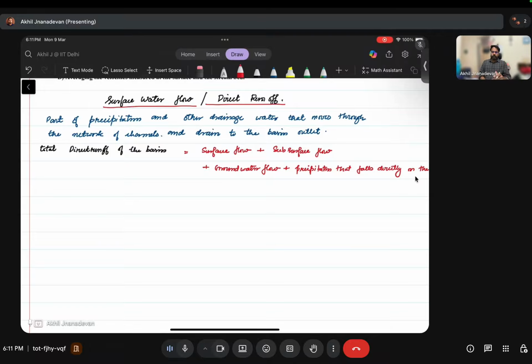Now we will be coming to how we can measure this, right? For precipitation, we saw how we can measure it. We were using rain gauges, and different types of rain gauges we have also discussed. When we came to evaporation, we saw how we can measure evaporation, like using evaporation pans or evaporimeters. And when we came to infiltration, we saw how we can measure infiltration. In the field, we can make use of the single ring or double ring infiltrometer, and in the lab, where you can actually have the sample, we can make use of the mini disc infiltrometer.